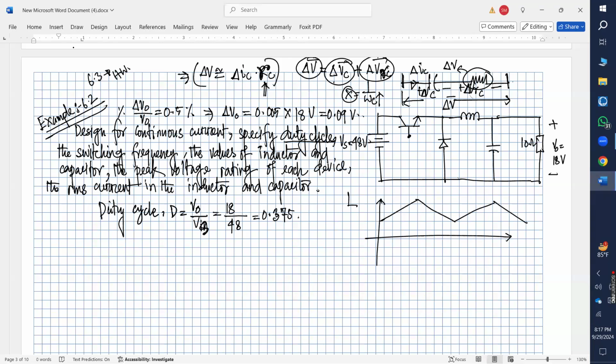So yesterday we were talking about the value of inductor current that can have effect of changing your inductance value, right? So we saw that if you decrease the inductance value, this current will shift downwards, right? And then we'll finally have an inductor value for which we'll have the extreme point of the continuous current, for which IL min equals 0.